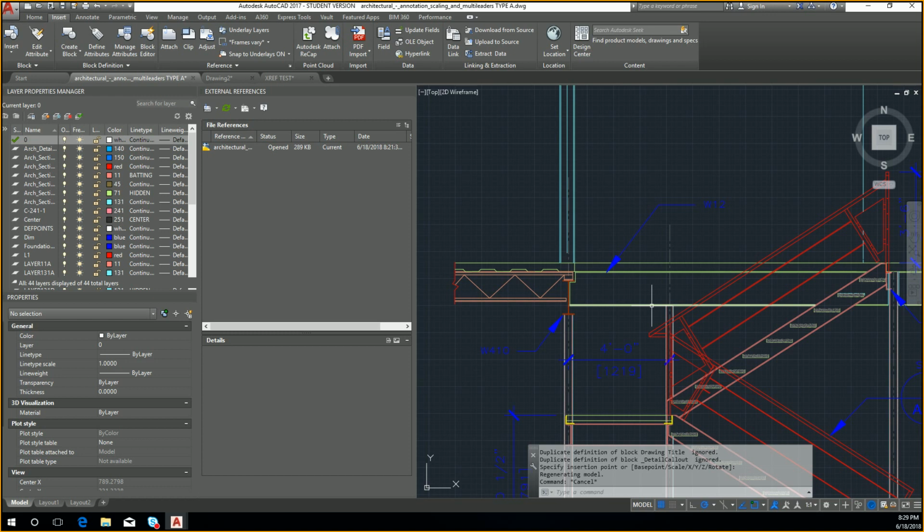So just in case you guys didn't hear that online, when you're attaching something, be careful which attach you're using. There are different versions, or sorry, different buttons that both say attach. One says attach under the reference section. One says attach on the point cloud section. So a point cloud is something where an object has been scanned, typically with a laser scanner.